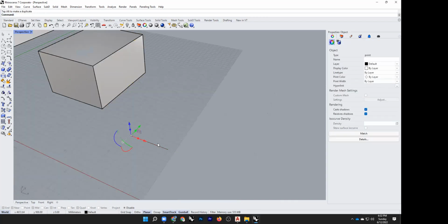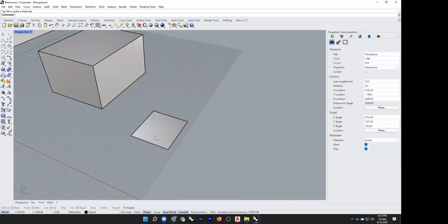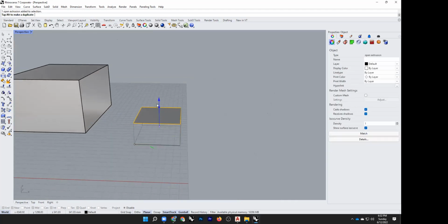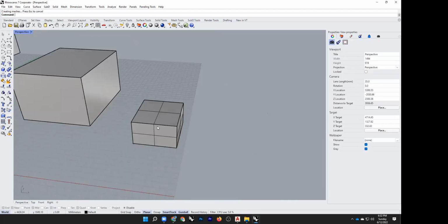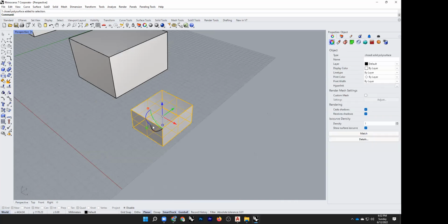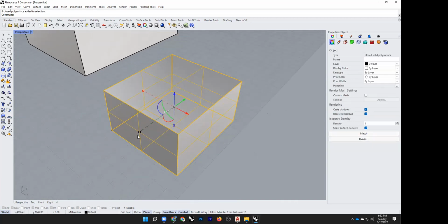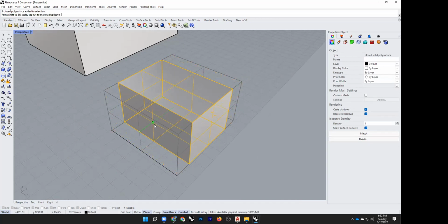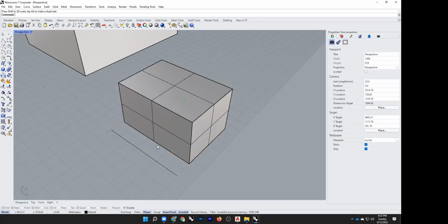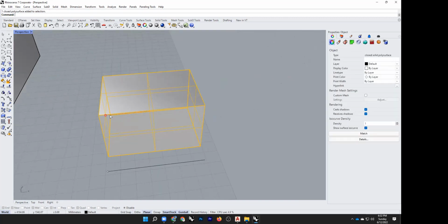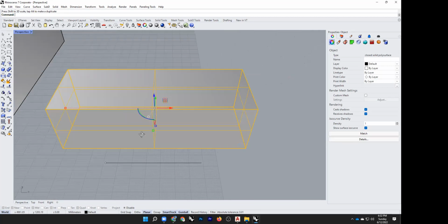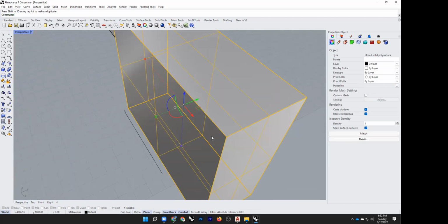Okay. So let me make a line and then a surface, and then we can make this a solid. And we have a few more options in Gumball. For example, here is this little square. What it does is it scales in the specific direction that you mentioned. So you can scale this in various ways.